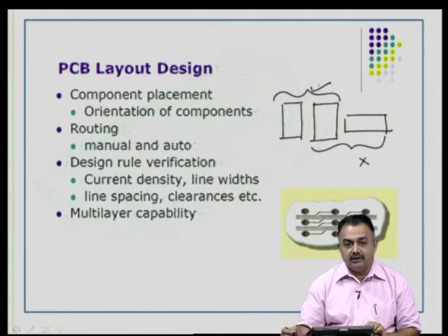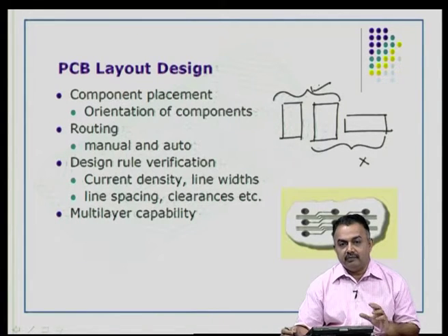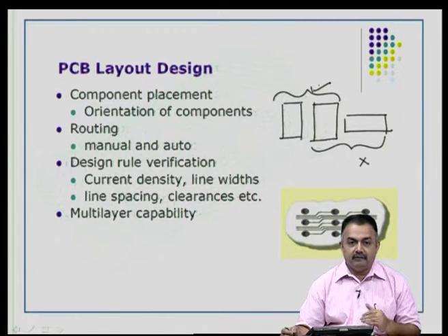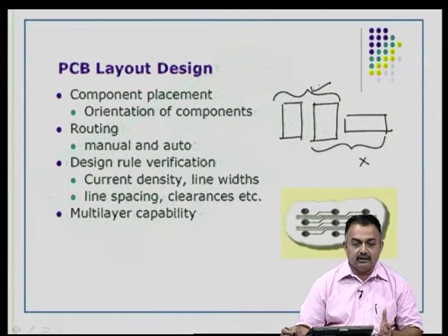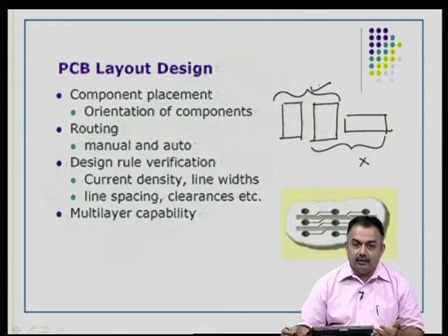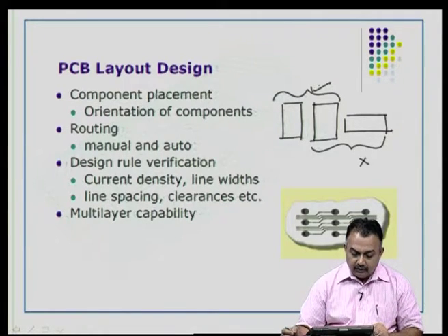Because there are various reasons for this. Not only just from the aesthetics point of view, it occupies more area, it provides difficulty in routing your traces, it provides difficulty during assembly of these components. Okay. So, the layout module will also contain